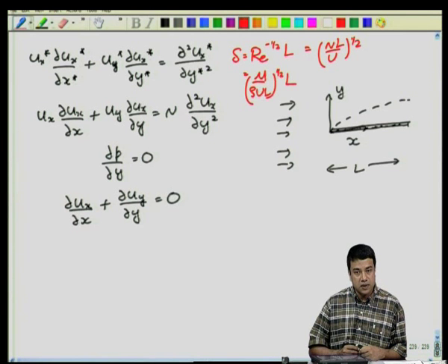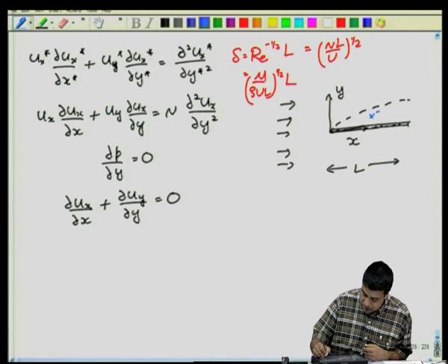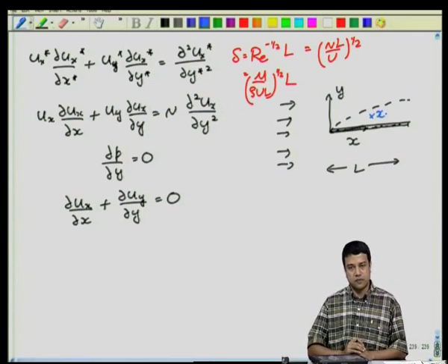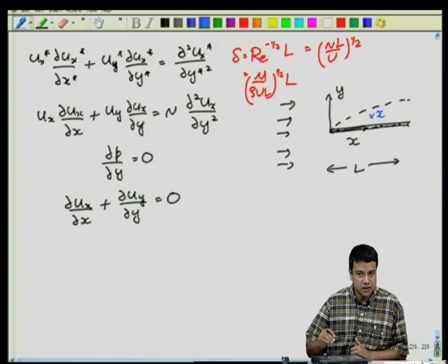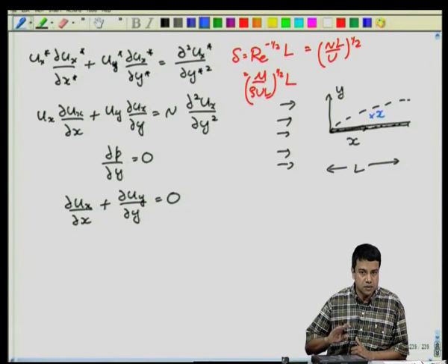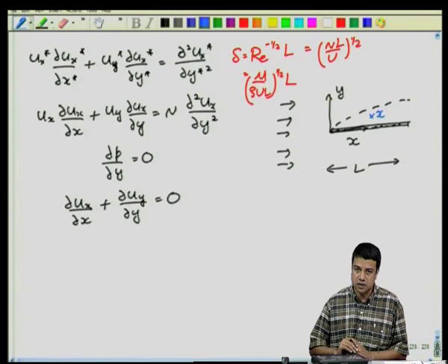When you include only streamwise convection, if I am sitting at a particular location x within the flow, the velocity field at that location x cannot be affected by locations downstream, because convection is sweeping through it downstream and I have neglected streamwise diffusion.